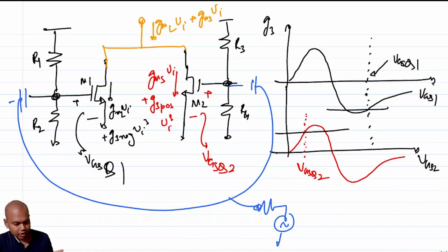Not only that, as it turns out, the range for which this cancellation happens is slightly larger than the case where you only bias at a sweep point. This technique is often called derivative superposition, because you are biasing two transistors which have different third order derivatives and superposing their characteristics.